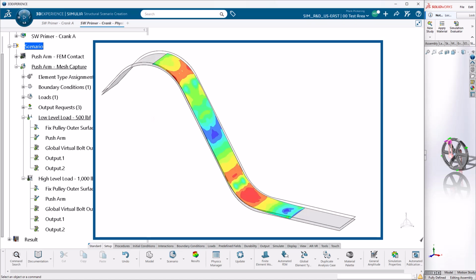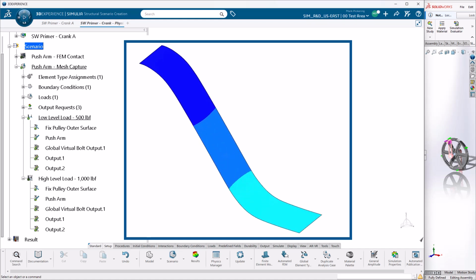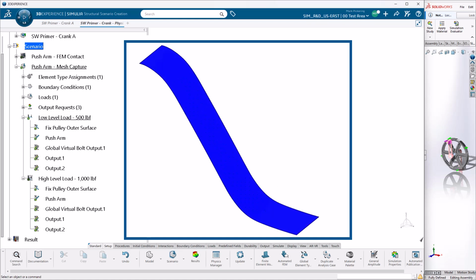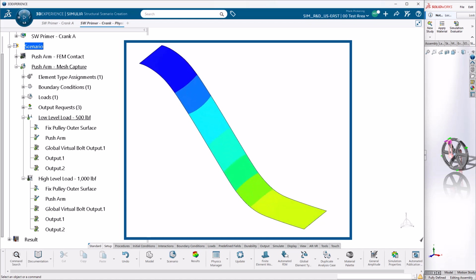However, once the strip has been formed, this isn't the final shape it will have. As the forming dies are removed, the elastic strains will relax and the shape will spring back slightly towards the original shape. We see that in this animation. This is significantly less nonlinear than the forming process, so an implicit static analysis is the more suitable approach for this.